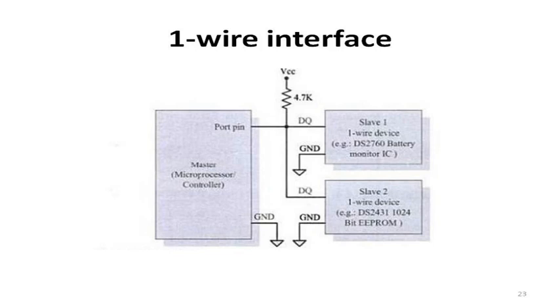To ensure proper power, electrically erasable programmable ROM devices may need a master that supports strong pull-up, a feature that temporarily bypasses the one-wire pull-up resistor with a low impedance path. The extra power is needed for the write cycle, and in the case of the DS1977, also for reading.